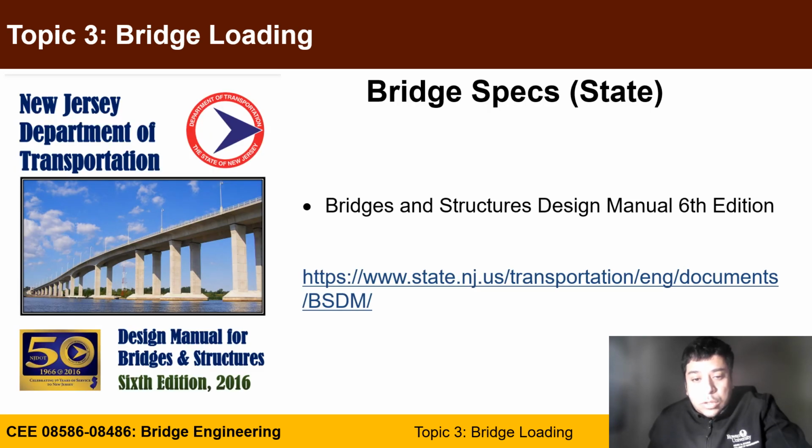We also will consider bridge design specifications from the state. Since we are in New Jersey, the most updated specification is from the New Jersey Department of Transportation, which is called the Design Manual for Bridges and Structures, BSDM. The link is here. It's open source, and the edition is the 6th edition, 2016.